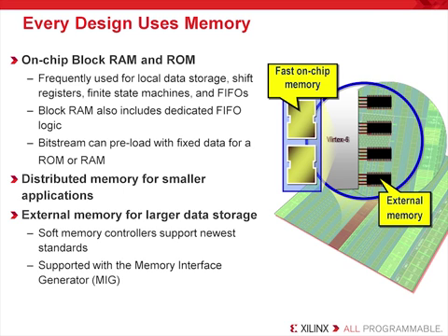All of Xilinx's dedicated memory resources, that is, distributed memory and block memory resources, can be preloaded with data, so when the FPGA is programmed, they already contain the memory initialized. And since these resources support both large and small memory construction, they only use the resources that are necessary for the size of memory you need to build. So they are both fast and flexible.